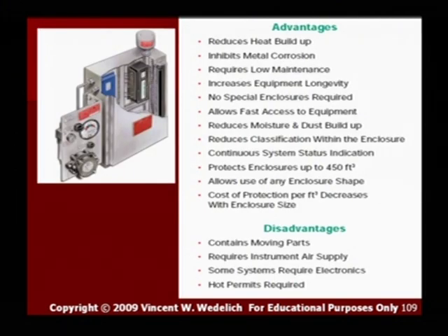And then now we have the purge, the EXP. Well, in NEMA terms, we don't call them EXP. We call it a Z purge, a Y purge, or an X purge. And we'll talk about that a little bit here. But here we have a regular box, an enclosure, and this is not anything special. This particular one happens to be a NEMA 4X, so that means that they can have a spray in any direction, and it's corrosion resistant because it's stainless steel.